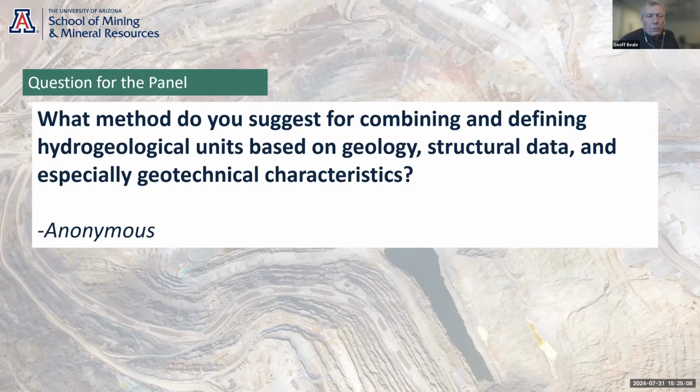So there's those two units, blast damage zone and the zone of relaxation. And then behind that, you've got the zone where there's no mining influence. So there's three zones there. The blast damage zone and the zone of relaxation we often combine into what I think you term, Lauren, the excavation damage zone, which has been adopted. But there's really three zones: blast damage, mechanical breakage, zone of relaxation, and then the zone where there's no influence.